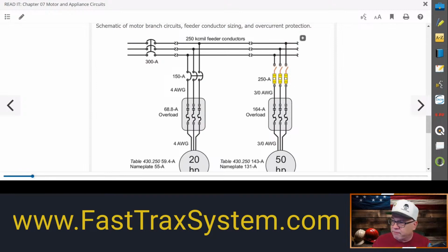So when we're talking about fuses, all we have to do, and in our lesson, it tells you the type of fuse. So you don't have to worry about that. We always want to tell you whether it's just regular, simple fuse, one blow, one and done, delayed, whatever, always given in our examples. For you, it's going to be very much dependent on what type of fuse you're dealing with, right? So in our case here, let's go on and look at 430.52 again, because we're doing short circuit ground fault protection. So let me get to it here.